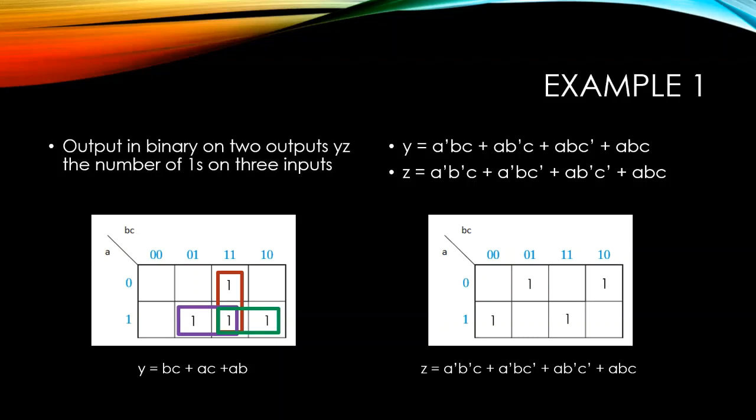But we could do something about this equation. So kindly review your XOR and XNOR as logic. So if we say XOR, we have X XOR Y. The expanded version is XY' plus X'Y, while XNOR is just the negated version of XOR. Okay, so by having that knowledge, we could manipulate the Z equation.